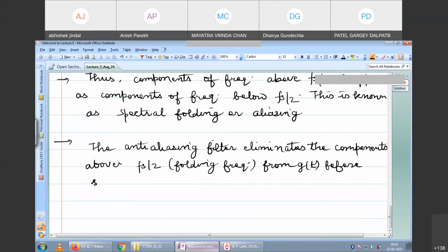So now with whatever I have explained, if you go back and read the textbook, and this is very important, this is called a hack which you need to do for real-time sampling. The hack means that you just pass it through the anti-aliasing filter before sampling. You will understand the reason behind it. And this is a very, very popular question.